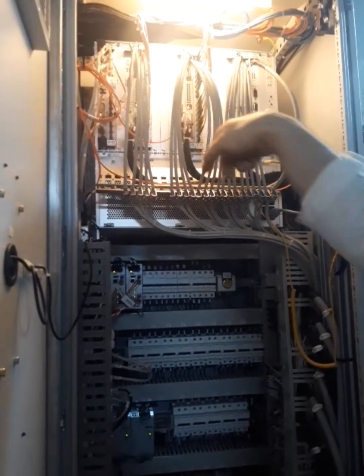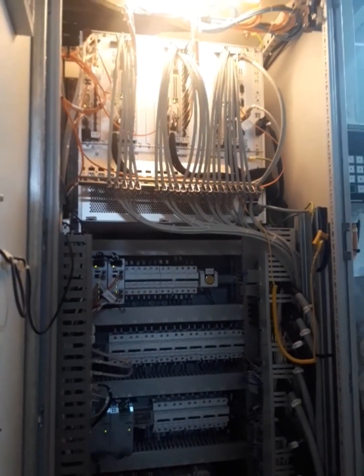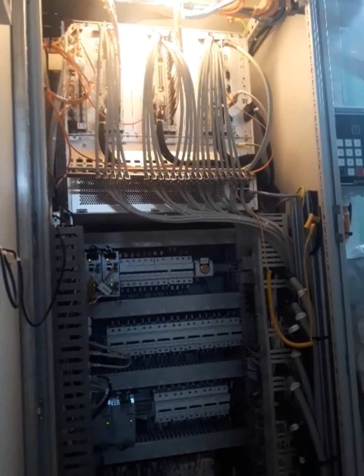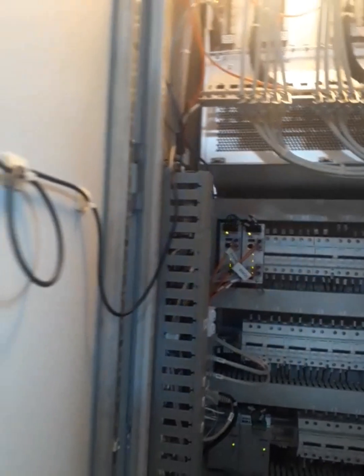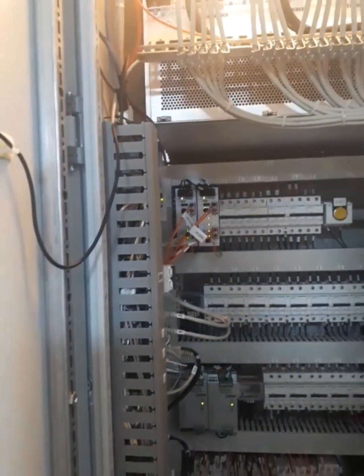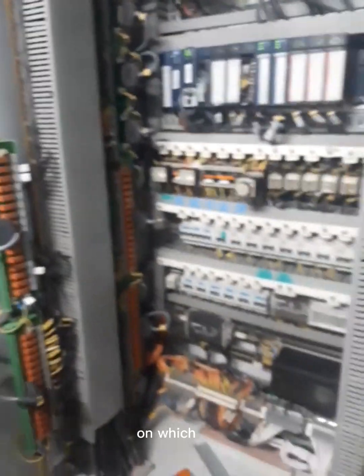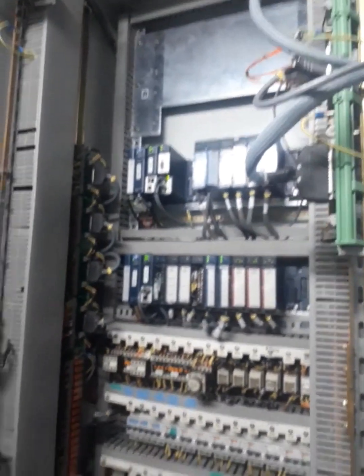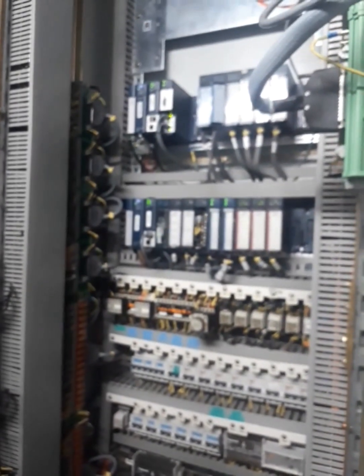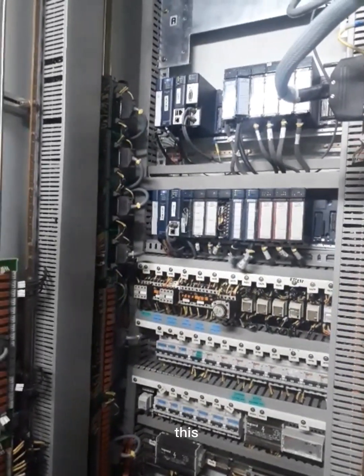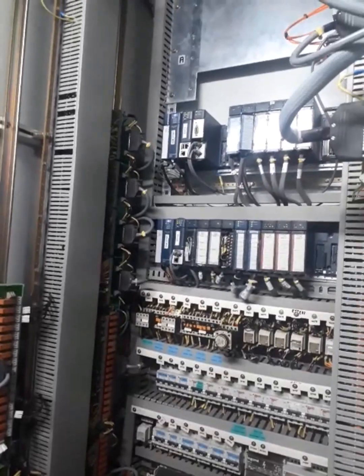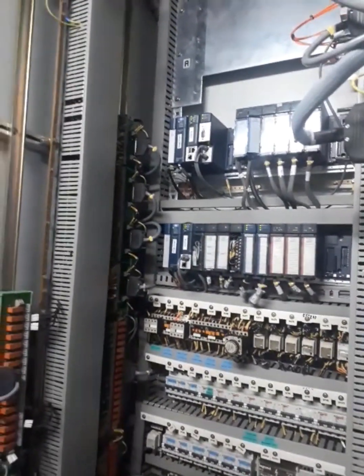The fiber optic cable is going all around the pod, and it's taking some data, calculating everything possible. Network bridge. Machine. So the command comes here first. When you want something on the bridge, it comes here first. For example, this is for half drive, half of the motor. All the signals from the temperature, some brakes, everything is processed by this PLC. And then from this fiber optic cable, see the orange one, going to the PEC. And the PEC is calculating how.